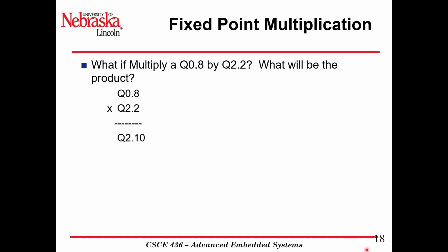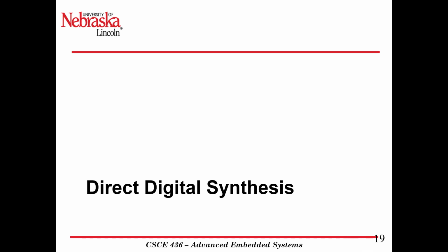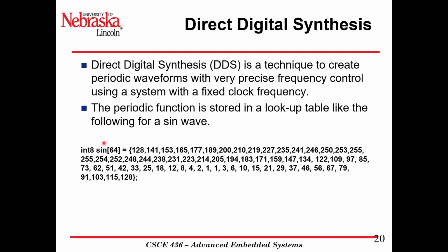Alright, next we are going to talk about direct digital synthesis. This is a technique used to create periodic waveforms with very precise frequency control using a system with a fixed clock frequency. We're going to store that function in a lookup table similar to this down here. This is basically an int8 sine waveform. So int8, it's only going to go up to values of 255. We're going to use all unsigned values.